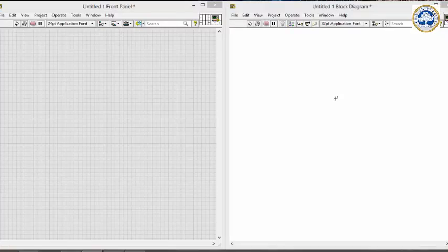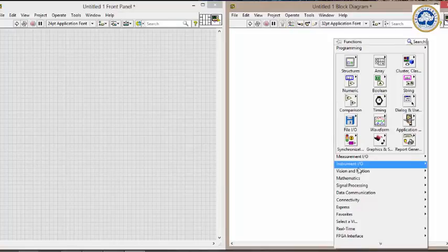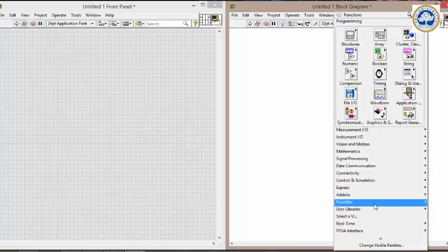When these steps have been completed, a Multisim design VI preview is made available to the user. Once the construction of the circuit has been completed, it is imported into LabVIEW. The Multisim LabVIEW co-simulation is carried out by using the co-simulation module. The co-simulation module is an add-on feature of LabVIEW that can be downloaded from the NI website.